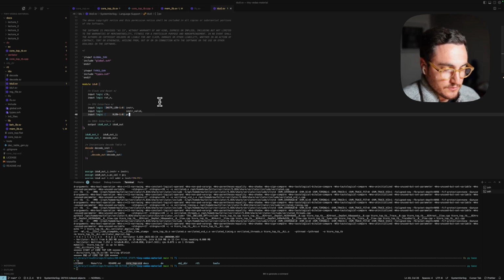So you can go look back at the code and see, oh, this is what should have been, this is what I get, let's go find the bug. So this is why we're passing down the program counter. On the bonus lecture on the FPGA, we're going to see how this program counter can be removed from synthesis when actually synthesizing the processor, because it's going to be needed only for debug purposes.